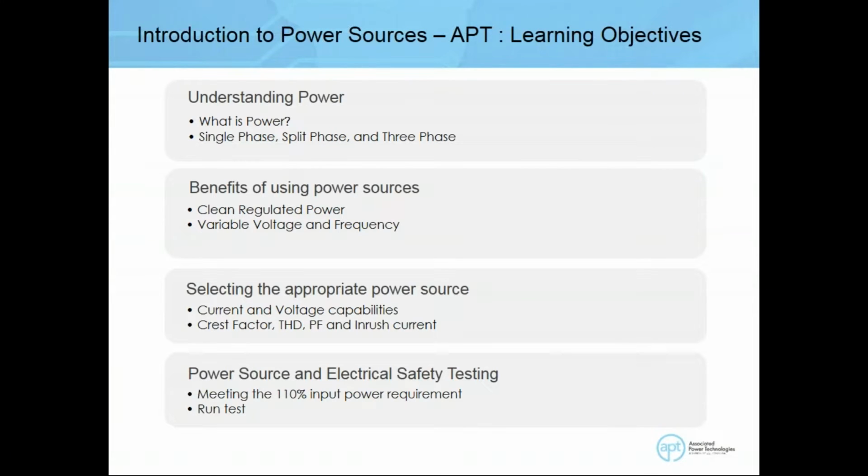And in the end, we're going to look at some of the standards that specify using a power supply beyond the normal requirements. So there may be requirements to run your products at 110% of the voltage. Nominally, this 110% voltage is not available from the wall outlet.